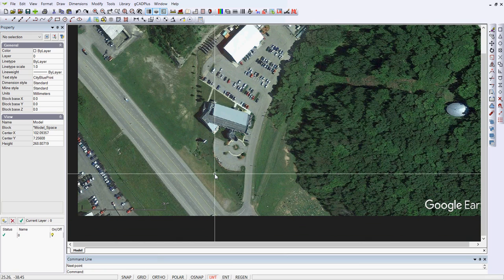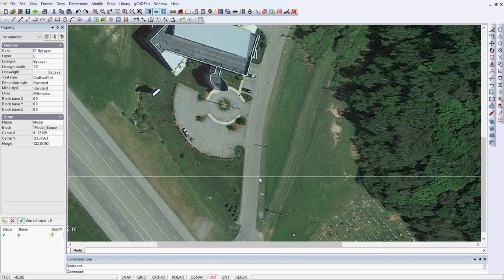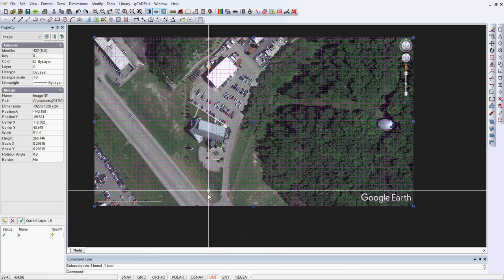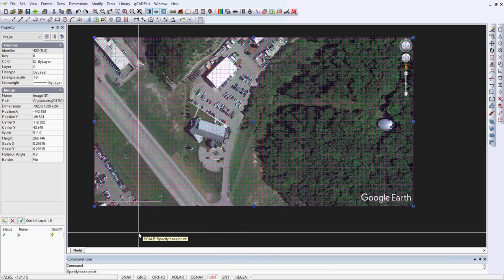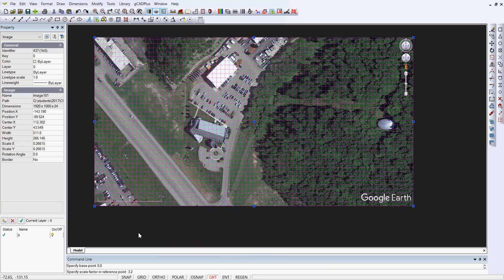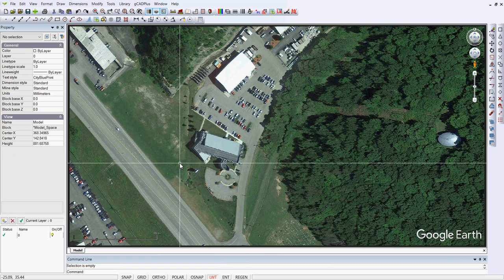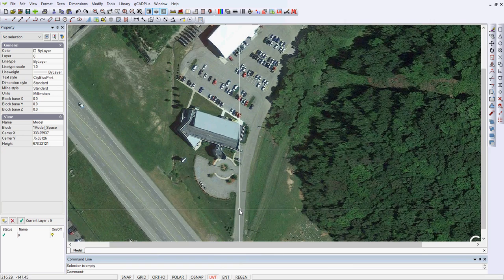So we know that with this drawing, we're thinking now in metres. If we wanted to measure the width of that access road, from one side of the access road to the other, it's 8.5 metres wide. But since this is the US example, what we now want to do is convert metres into feet. Well, 1 metre is equivalent to 3.28 feet, so if we select this, right-click scale again from 0, 0, and scale it up by 3.28, and we zoom extents again, we've now got a drawing that should report back to us in feet.